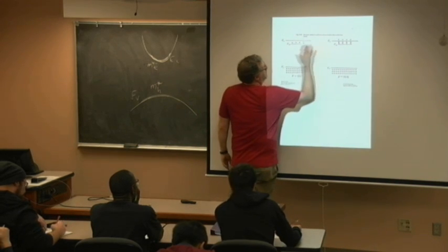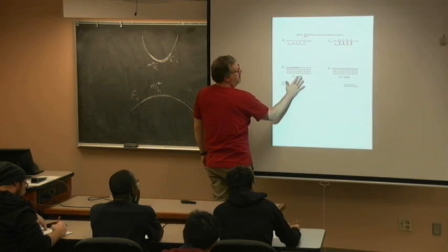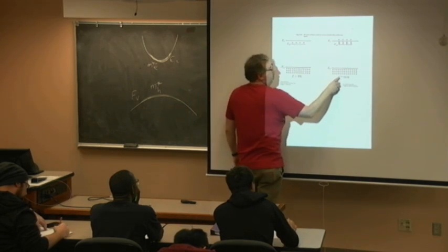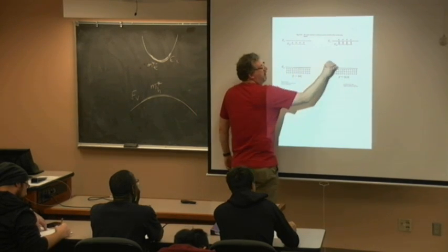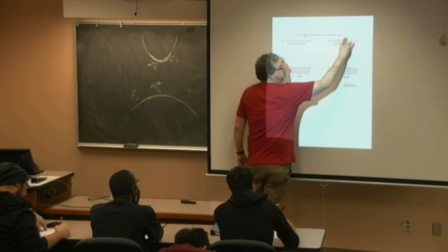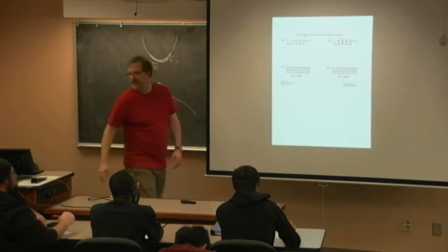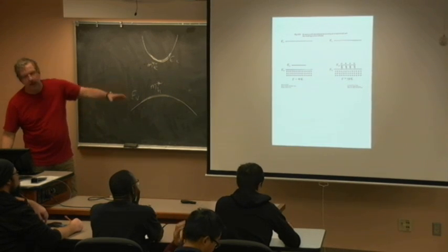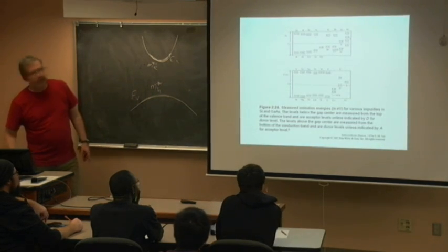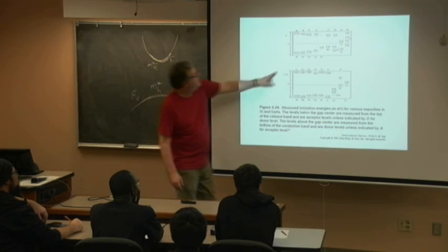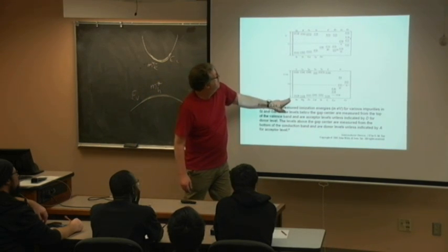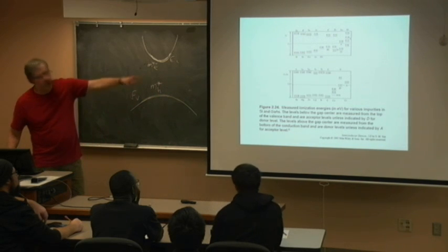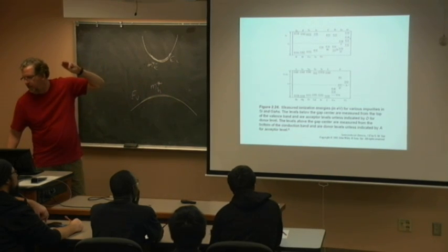So this is what it is at cold temperature. The phosphorus atoms has that fifth electron, but at kT starts to become finite. That extra electron just runs away. And here's similarly the acceptors. So this shows you what you want to choose. This gives you one of those three criteria for a good dopant.